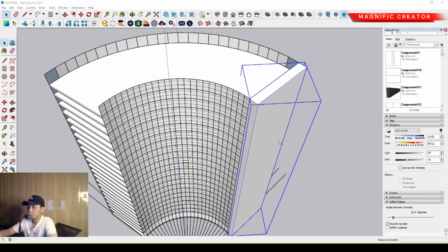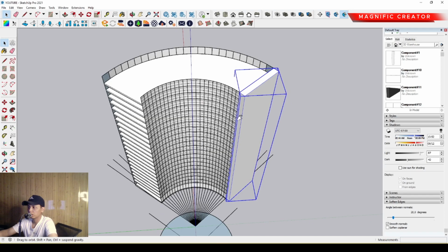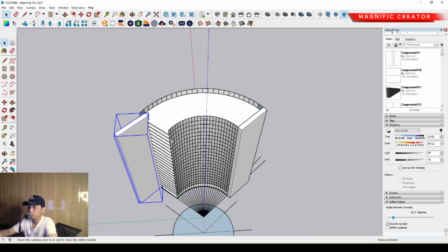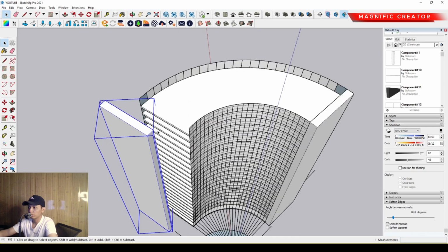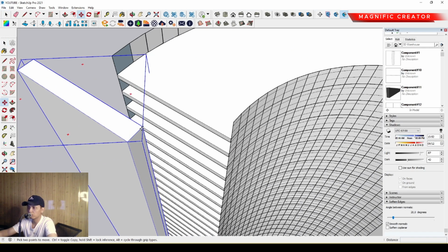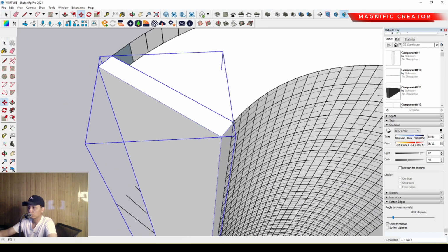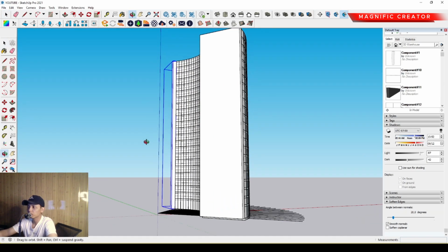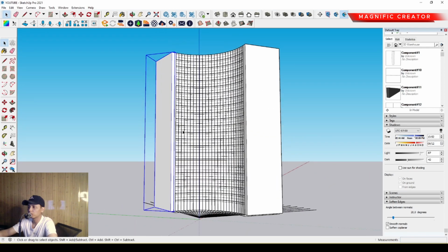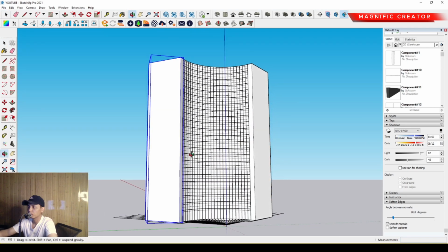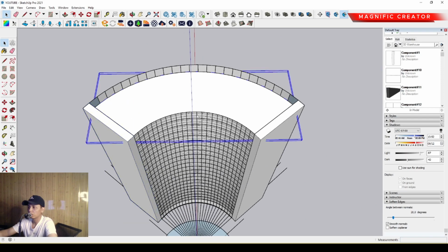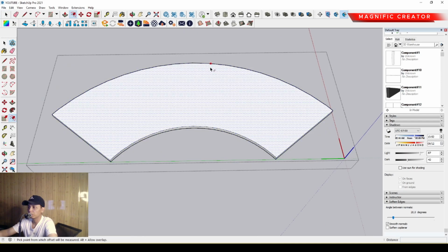So, and then we can make it component, create, and then we can move and press Ctrl to another position, and then we can flip it along with the green axis. So then we can move it to the correct position over there. Okay, and it's done. And then okay, we can make the top floor unique. So then we can make the core building anyway.